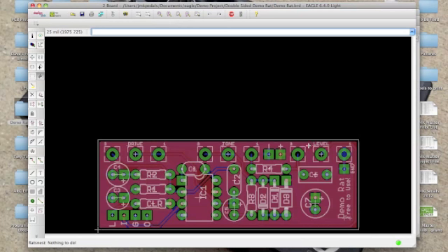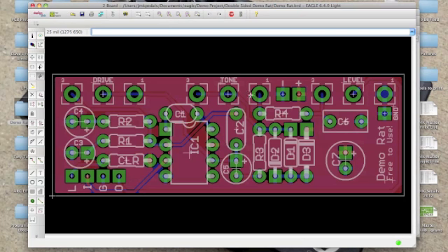So yeah, this becomes really, really handy, mostly when the graphic interface isn't quite right for my layout. The pad size is a little bit too small when I'm doing, say, a single-sided layout, and I need my pad to be a little bit bigger because my drill hole size just about removes all of the actual pad and then it disappears. Or if you got a bunch of boards back from OSH Park and you can't actually fit your leads through the holes, you have to edit your parts for try number 2 and that sort of stuff.